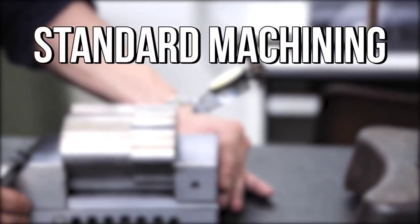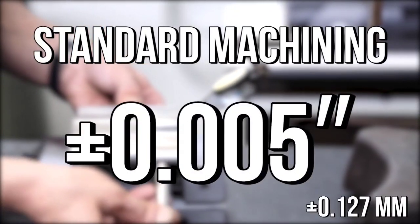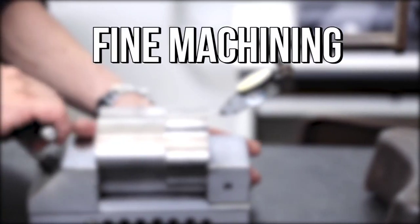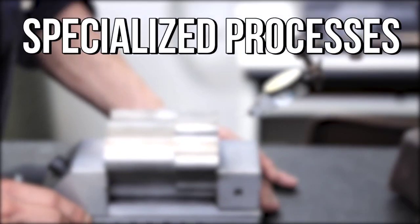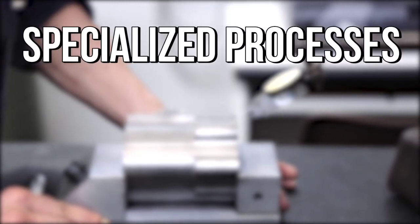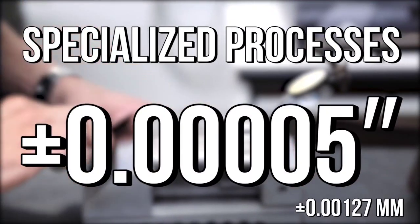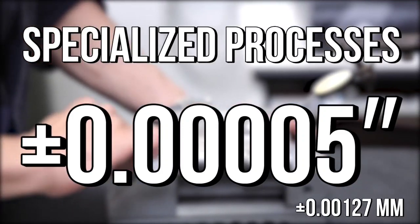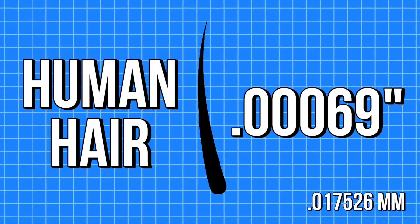Standard machining can provide tolerances on parts around plus or minus 0.005 inches. Fine machining can produce tolerances of about plus or minus 0.001 inches, and specialized processes like polishing can offer up repeatable tolerances as tight as plus or minus 0.00005 inches. For reference, a human hair is 0.00069 inches thick.